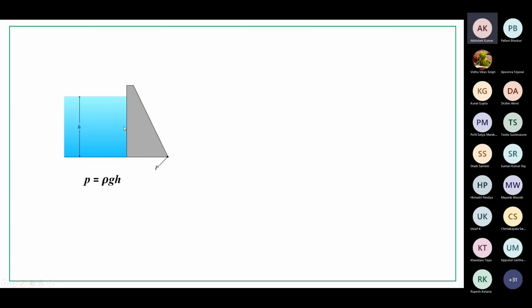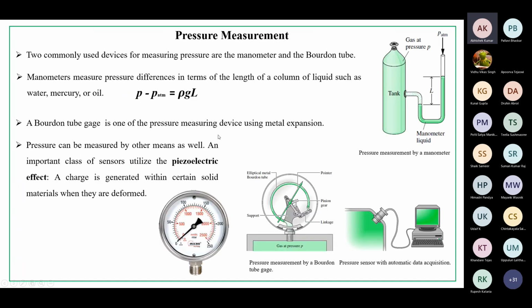The reason is this. This is the water, and pressure we define as rho g h. The density of the water is the same, 1000 kg per meter cube, and this is obviously gravity. With increasing depth, pressure is increasing. Here pressure is less, here it is moderate, here it is very high. Wherever pressure is high, force is very high. To sustain that much high pressure, more material is required. That is why material is also added over here. This is about understanding the pressure.